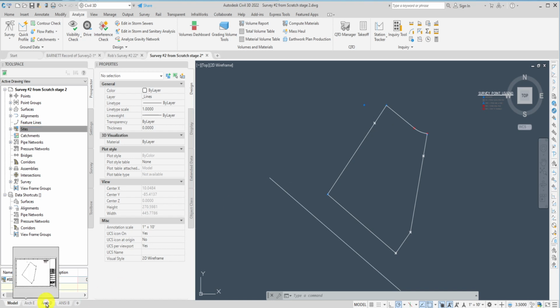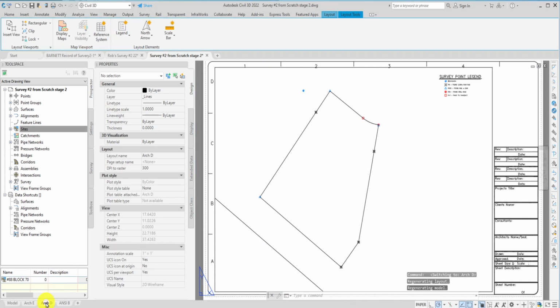So I'm going to navigate back to the layout. And one of the things in Civil 3D that is part of a file setup is called creating a site. And it has nothing to do with, let me think about this, yeah, it has nothing to do with geometry. It's a database function. And before we put any geometry in, we need to create this site. And we'll talk through this quite a bit, but